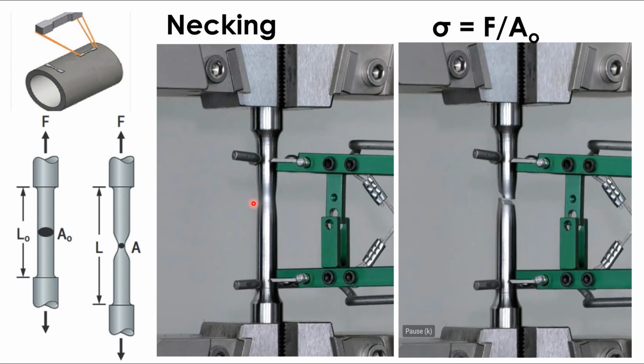The length of the rod will change from L to delta L, and the area of the rod will start reducing. When we increase the force, the area of the steel rod decreases, and this is called necking. At this point, the rod will break into two parts, and the area at this point shall be negligible or zero. It means stresses at that point will be ultimate.